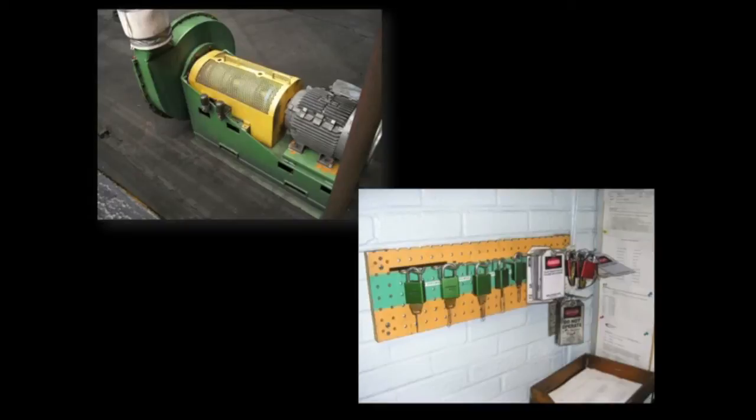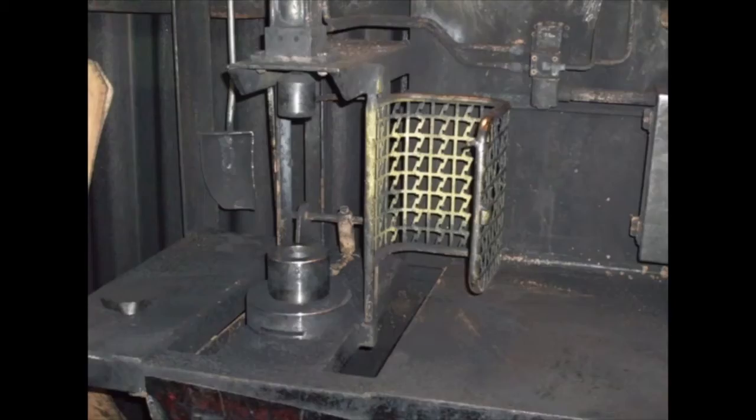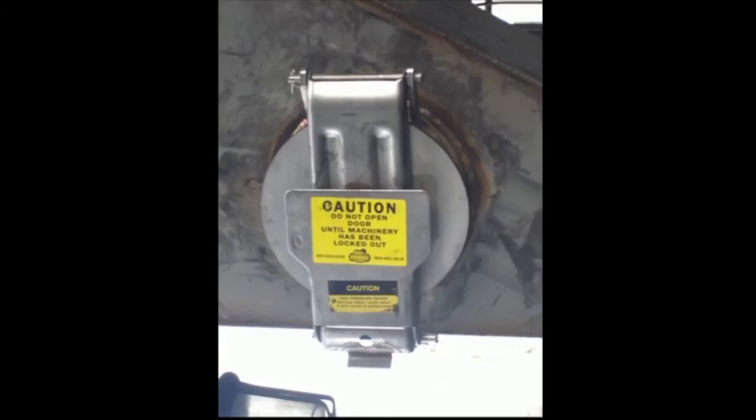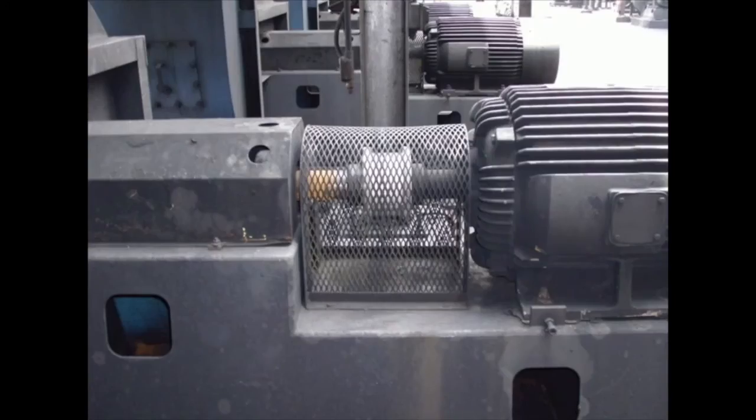There are two controls needed to protect against the hazards of moving equipment. The first is machine guarding. The second is lockout-tagout. Machine guards are physical barriers that keep clothing, hands, fingers, and other body parts from becoming entangled in moving equipment. Individuals should never remove machine guards unless specifically authorized. If removal is authorized, machinery should be stopped and de-energized first. Once the task is complete, guards must be replaced.